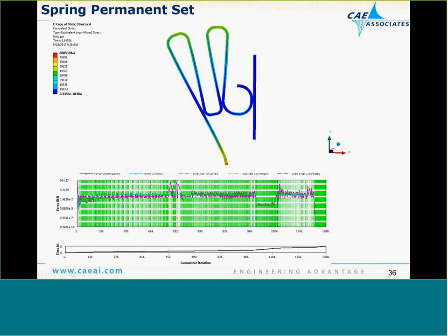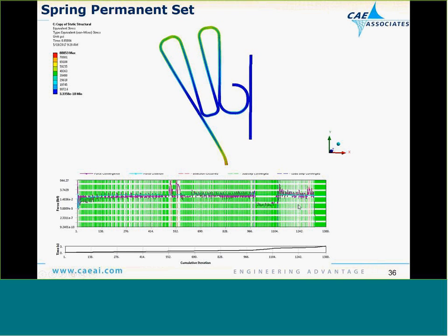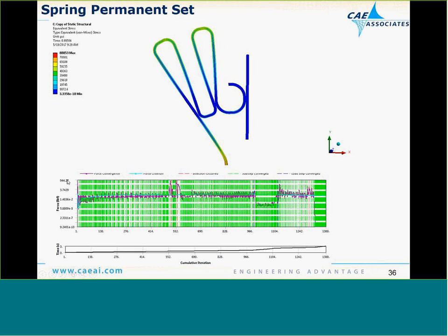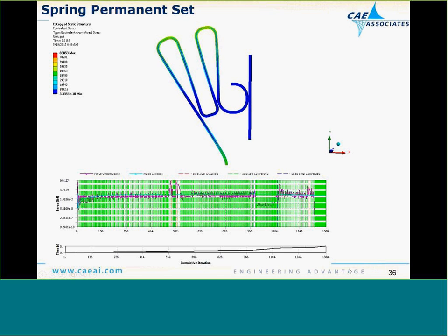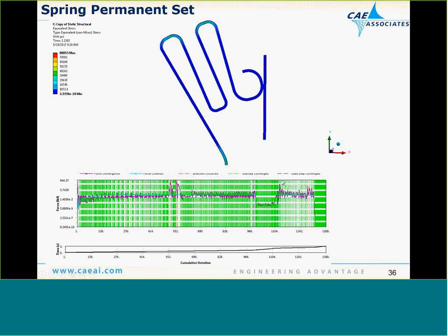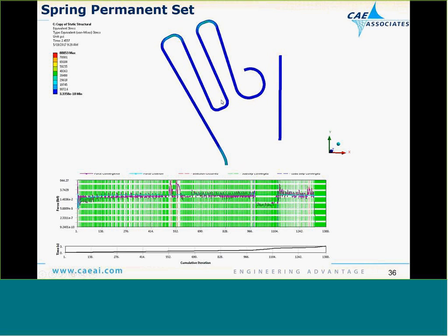You see in red, there's a couple places where it did some bisections, but by and large, I just ran lots of intermediate solutions. You also see here why starting with a simplified model makes sense, because I'm running 1,400 iterations. Well, I can do that with a simple finite element model much easier than I can do with a complex finite element model.